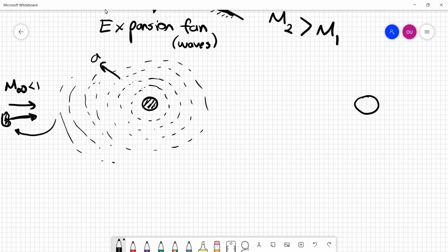So what happens in subsonic flow, for example, when you draw a streamline, you see that initially they are perfectly horizontal, and they will start to deviate from being horizontal such that fluid particles will adjust themselves even before they reach the solid object, so that they will move around the object.